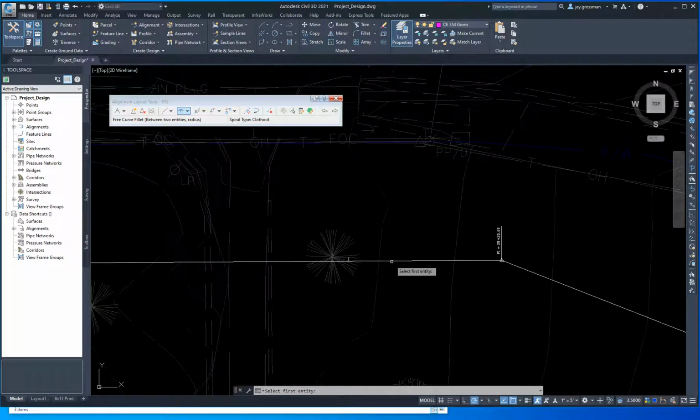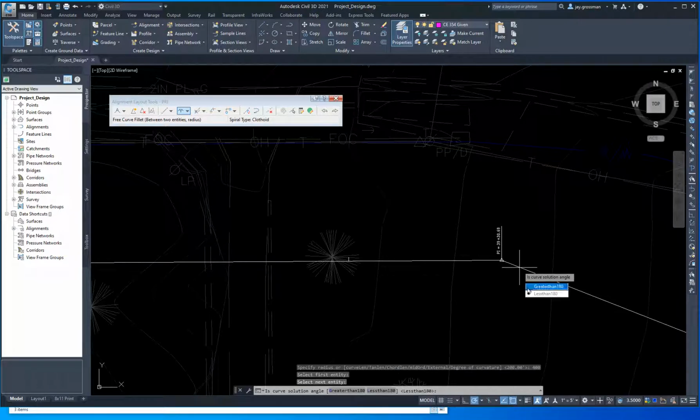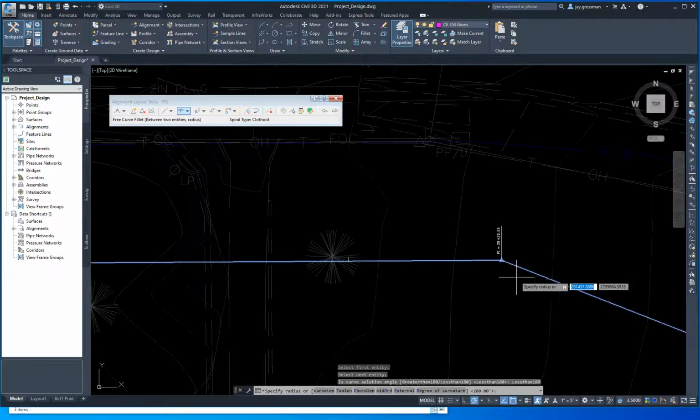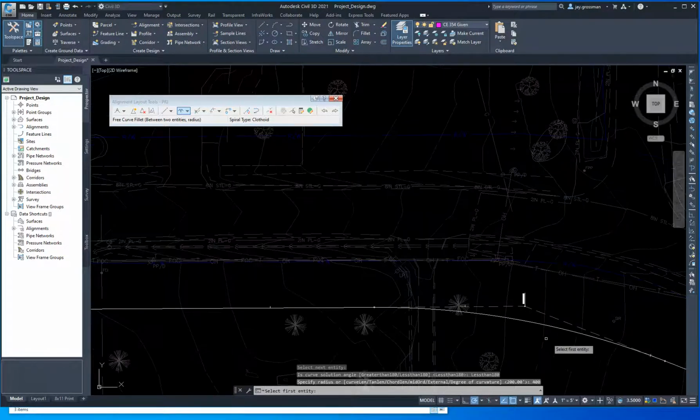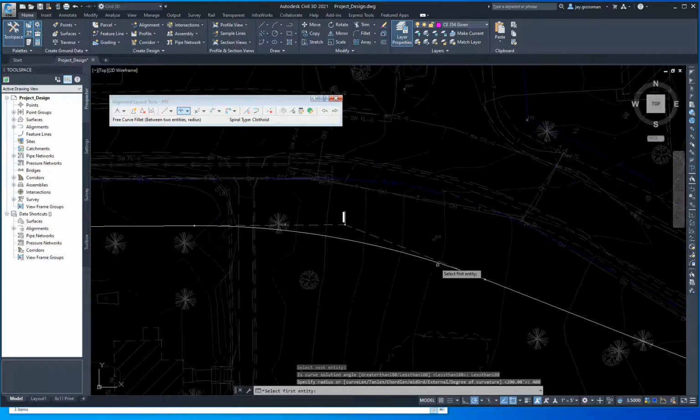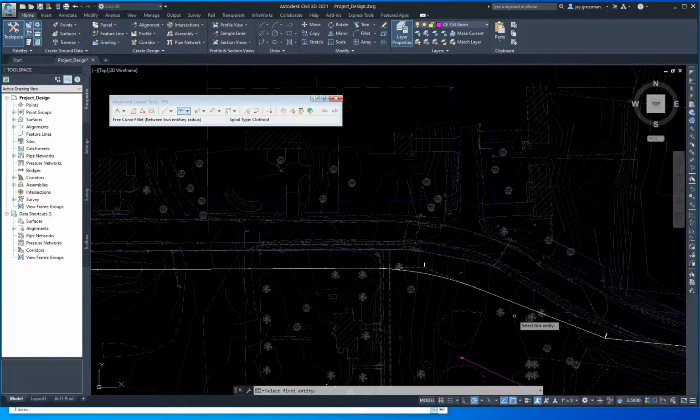How about down here? This is a much sharper angle, a much larger delta. And 180. Let's keep this. Let's go 400 again. Now, a 400-foot radius here, it really makes a difference because this is much larger delta, much larger change in angle as we go through that.